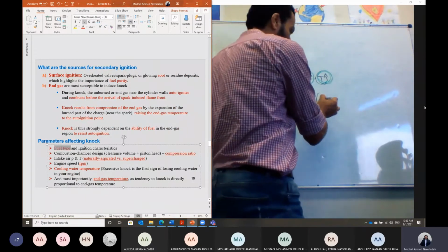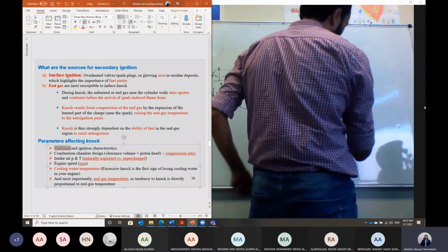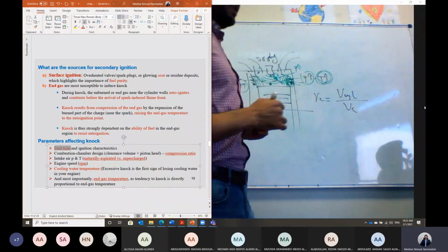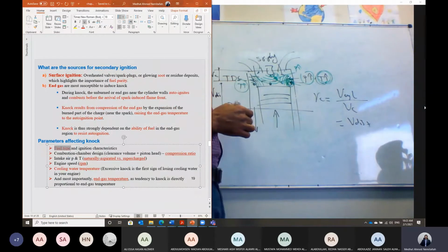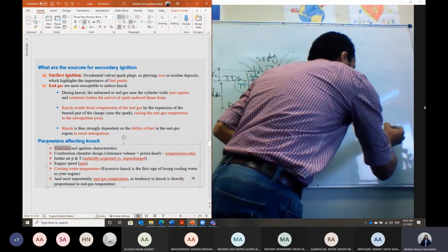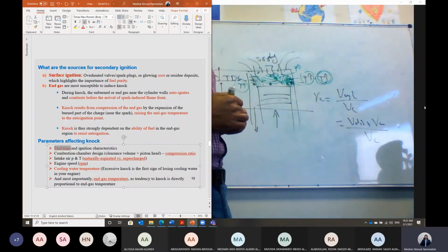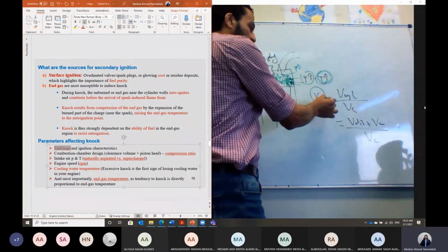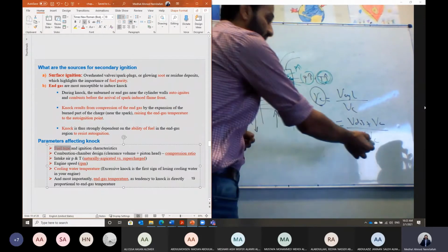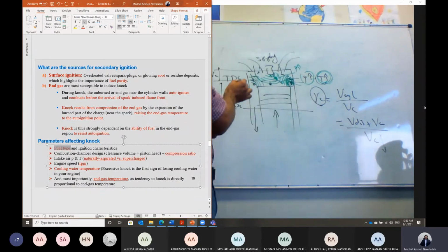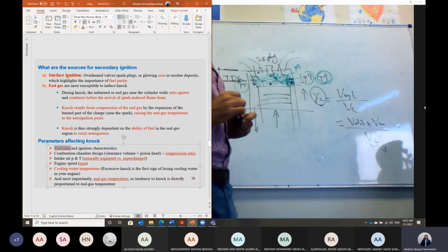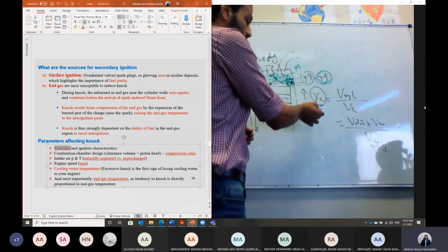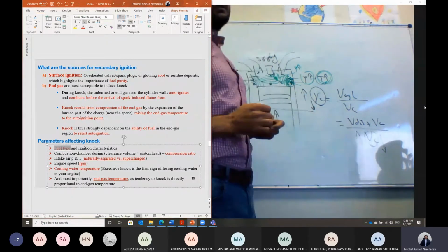While the stroke of the piston gives the displacement volume, we have defined the compression ratio of the engine to be the cylinder volume divided by the clearance volume. The cylinder volume is the displacement volume, while the piston moves between the bottom dead center and the top dead center, plus the clearance volume, divided by the clearance volume. So if the engine is designed to have a higher compression ratio, then we have to reduce the clearance volume, which is the volume between the top dead center and the cylinder head. If it is low, then we can raise the compression ratio of the engine. If we need to reduce the compression ratio, then we can increase the clearance volume.